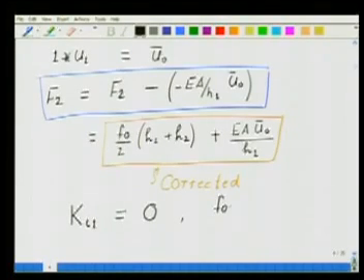This is for i equal to 2 to, for our problem, 6. Certainly, we are not going to do this to the first row, because then it makes no sense. From the first row, we want U1 equal to U naught bar, and from the second row onwards, we want to take care of this known value of U naught by suitably modifying our load vector.